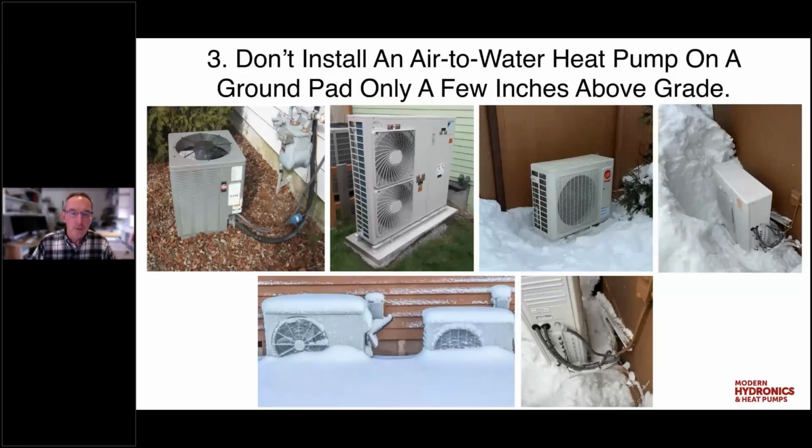In the middle here, we've got a unit that's on a very shallow concrete pad. That was installed in a warmer climate where they really don't get much snow. It probably would be okay from the snow standpoint, but still getting it above grass clippings, getting it above just anything that is on the lawn is going to help keep that coil clean.